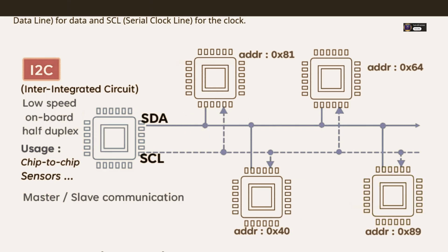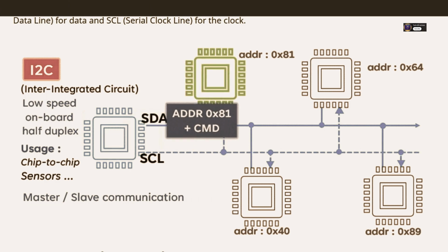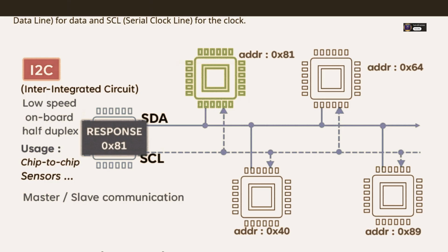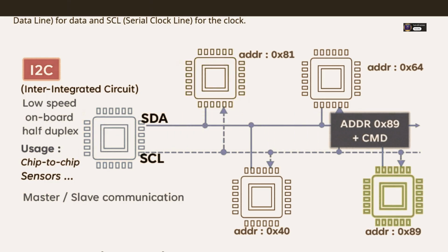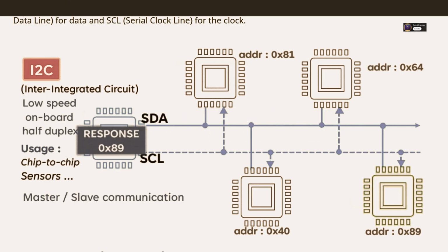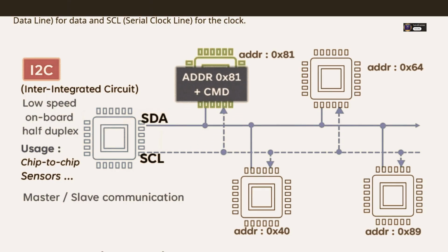So how does the addressing work? I know there's 7-bit and 10-bit addressing. What's the difference there? Yeah, 7-bit addressing is the standard, the most common you'll find by far. It uses 7 bits for the address, which allows for up to 127 unique device addresses on one bus. Address 0 is reserved. That's usually plenty for most systems.